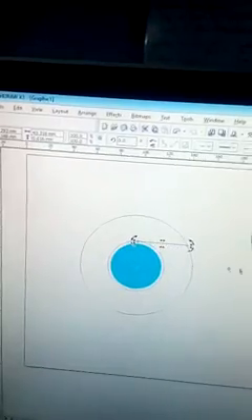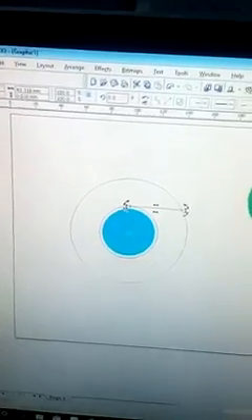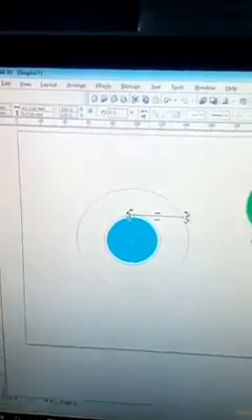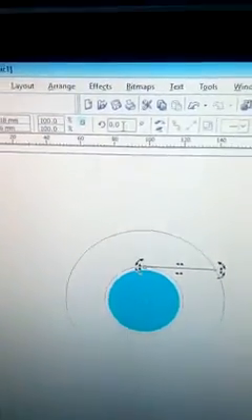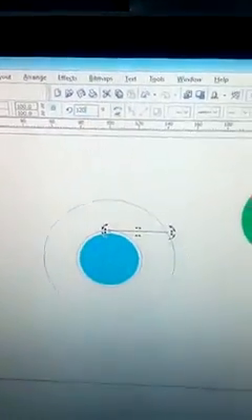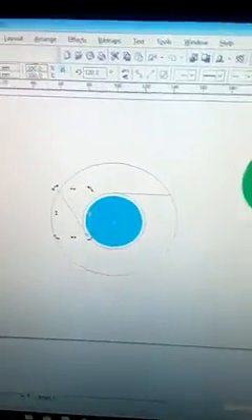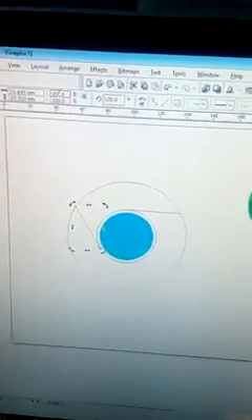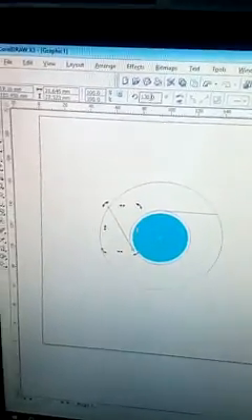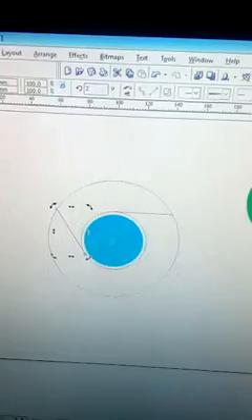So next we have to duplicate this object. And how can we duplicate? Remember, you can use Ctrl C, Ctrl V to duplicate, or you just press plus. I'm using plus on my keyboard. Then the angle of rotation here is set to 120 and press Enter, and it automatically gives us something like this. So I have to create one more by duplicating this by pressing plus or Ctrl C, Ctrl V and go here, change it from 120 to 240 and press Enter, and we have this.